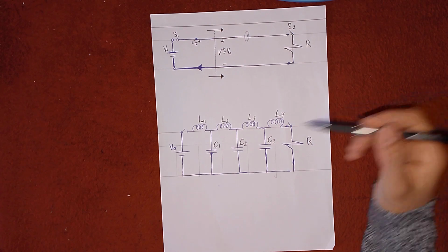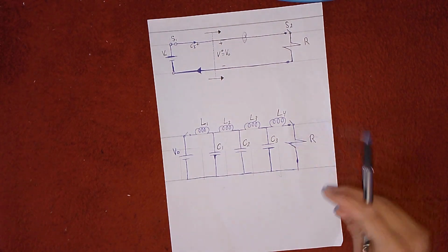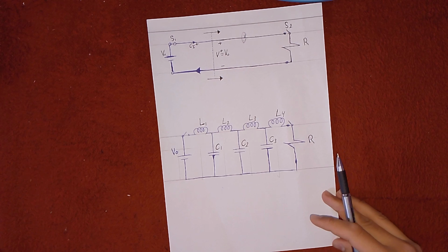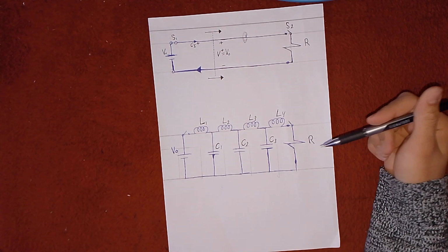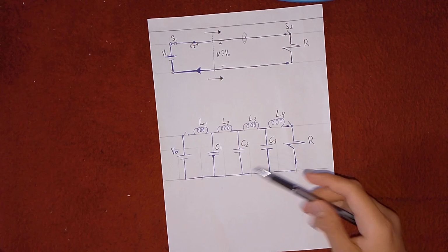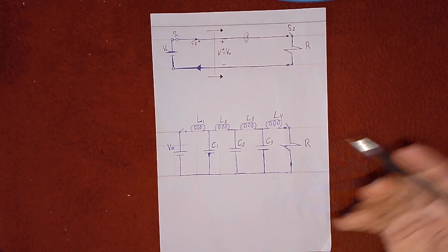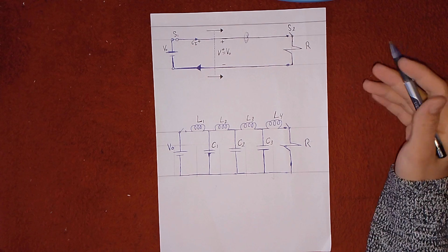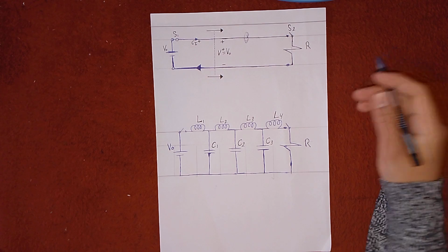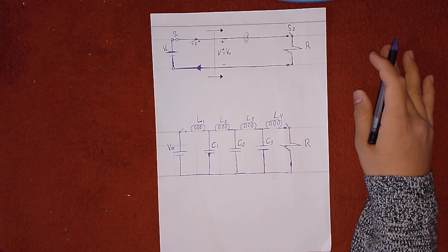This progressive charging process continues down the network until all capacitors are fully charged. As the charging process continues, the wavefront moves from left to right, and its speed depends on how fast each inductor can reach its full current state, and simultaneously by how fast each capacitor is able to charge to full voltage.